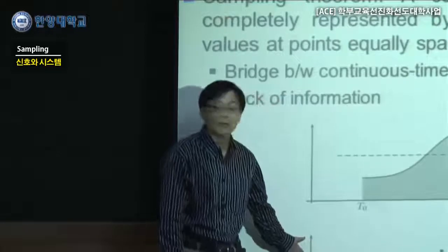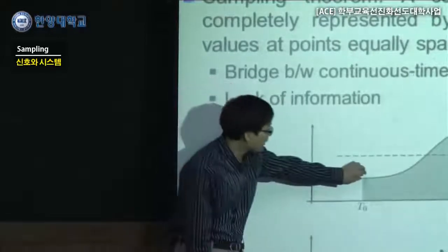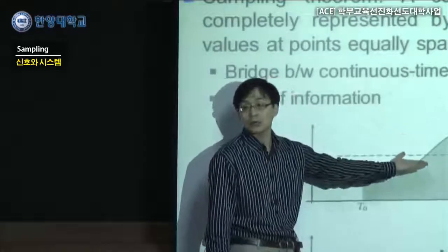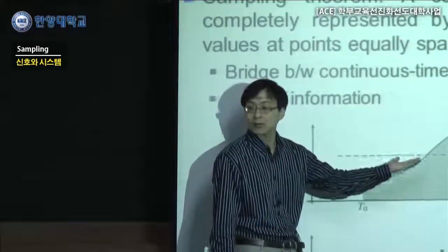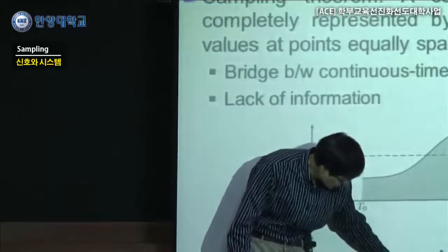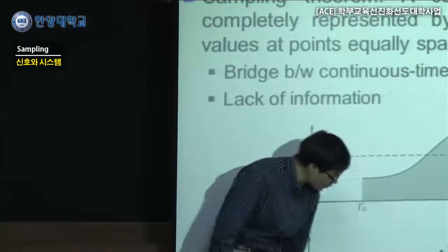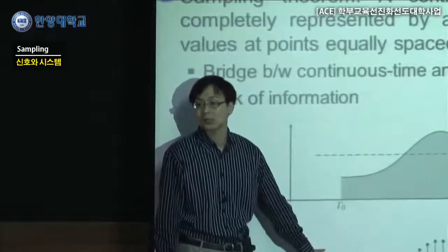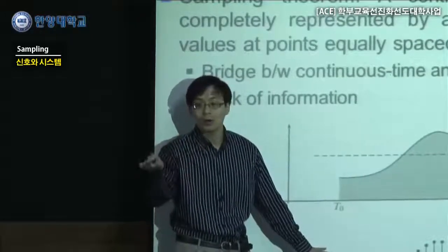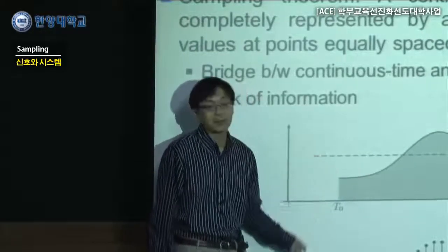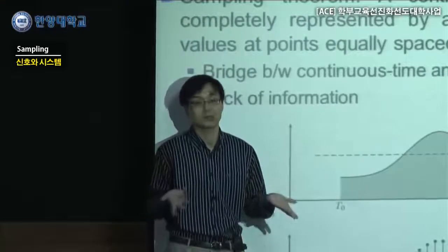This is a discrete time signal, which is where we pick up values from a continuous time signal at certain time spacing. So in the time domain, which is the x-axis, this is discrete. We can count the number. The value of the y-axis is still continuous.